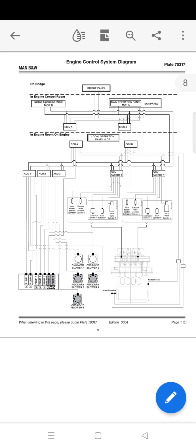This is normally done via the request acknowledge facility of the remote control system. However, it is possible to override the normal changeover procedure by means of the force take command push button. Activating the button will force control to the local station.